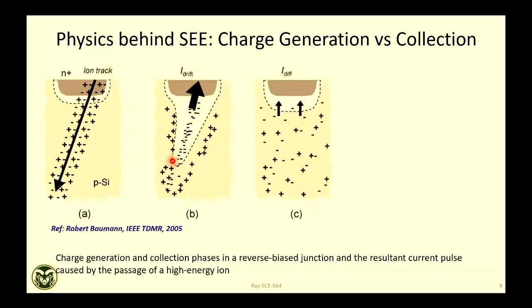And then, so the p-n junction is expanded locally, right, because of these holes, you get a local potential, right? So your p-n junction depends on what is so like reverse bias. With those holes, it's more like a reverse bias junction. So that's why the junction is expanded or your collection area is increased. And then at a later time scale, say hundreds of picoseconds, in that time scale, there will be diffusion taking place. So diffusion will take over the last phase.